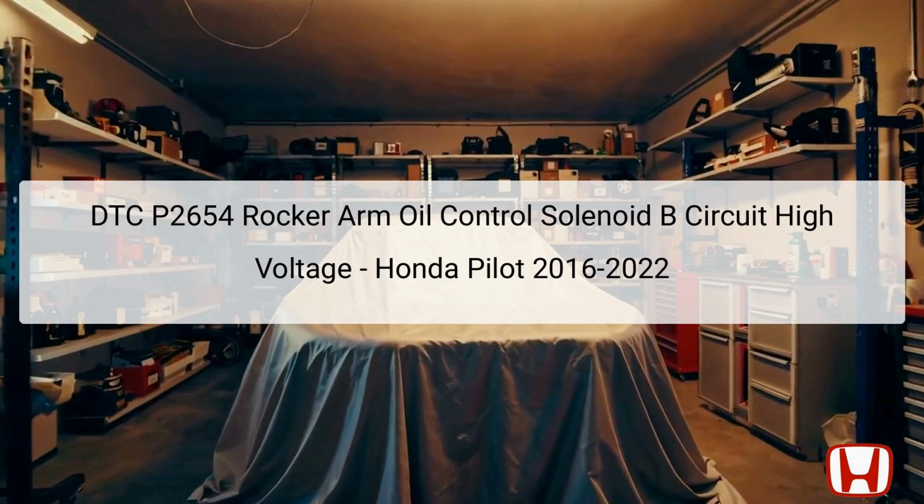The Honda Pilot from 2016 to 2022 is affected by DTC P2654, which signifies an issue with the rocker arm oil control solenoid, B, on bank 1. This fault relates to a high voltage condition detected in the solenoid circuit, indicating potential electrical or component failures.